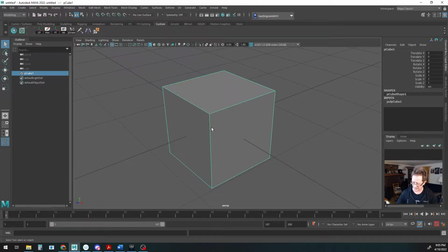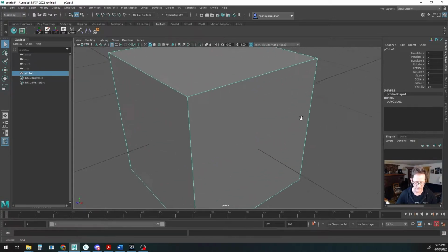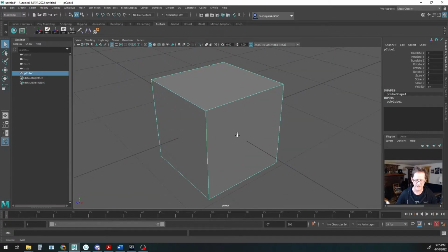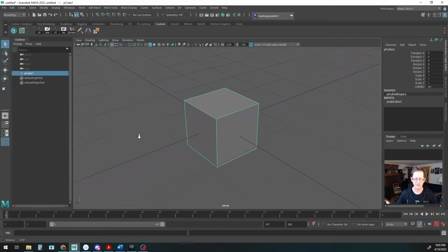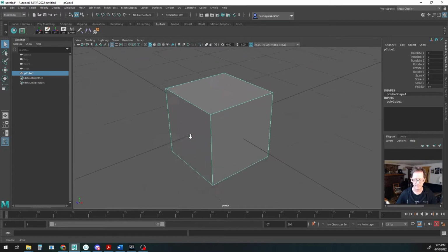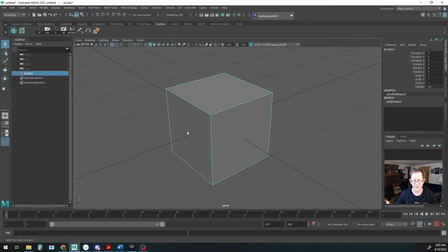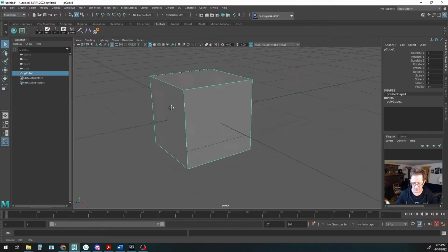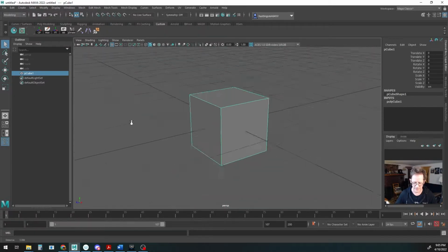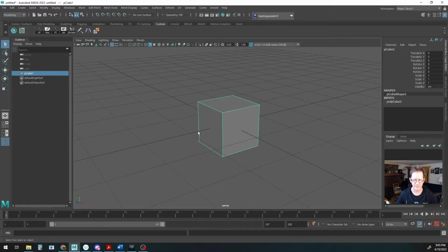So that's panning, and Alt and right mouse button, which I usually do with my middle finger, moving the mouse left and right, zooms it like that. I always tell the students, don't use the middle mouse scroll button. It's an easy thing to do, but when you get used to holding down Alt, left mouse button, middle mouse button, right mouse button, it gets to be a whole lot easier.